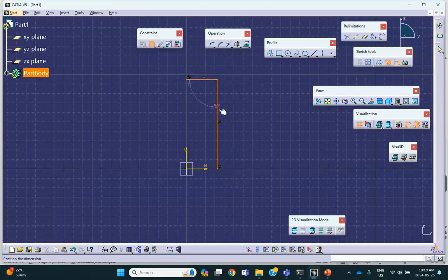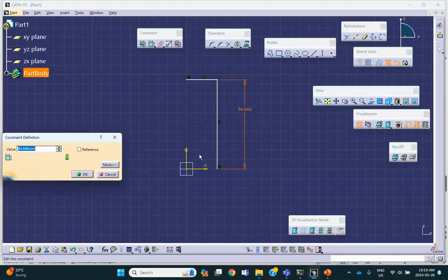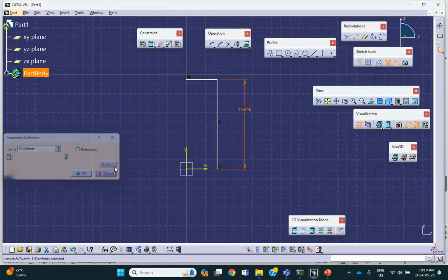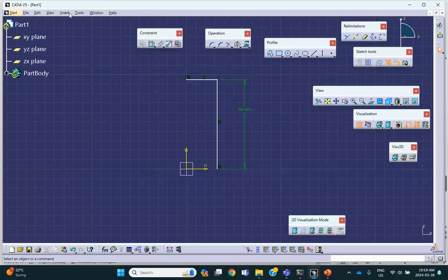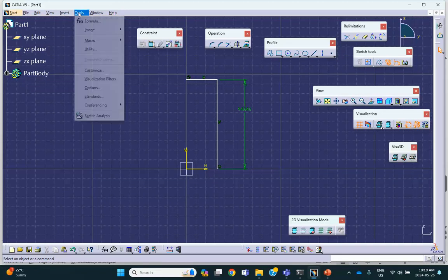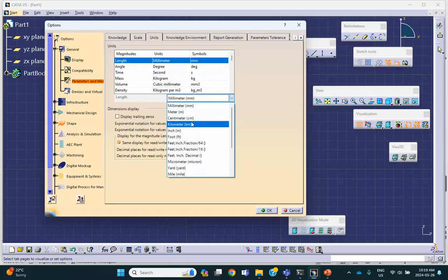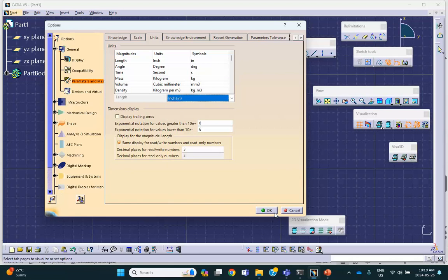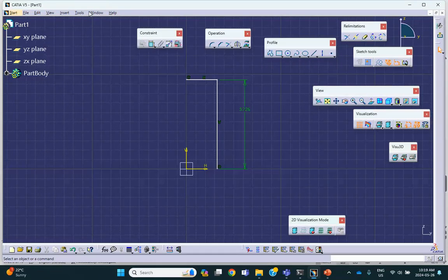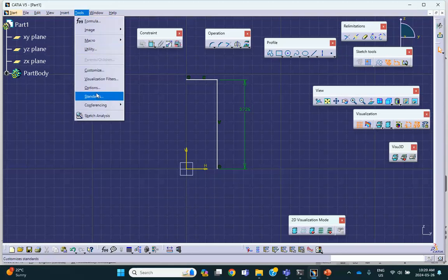So this is going to be 20 inches. Our units are in millimeters, which is not a good idea. Let me go ahead and change this. We have tools, options. Sorry, change the unit to inches. And pressure, I'm going to change it to PSI. Tools, options, I forgot to do that.